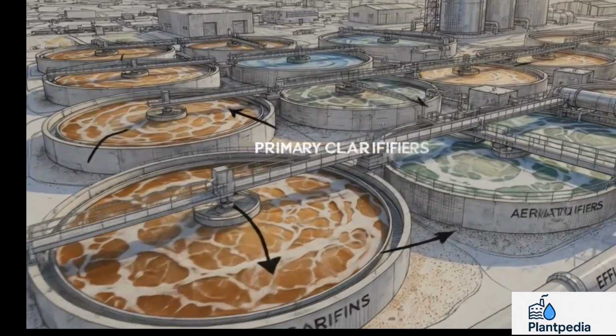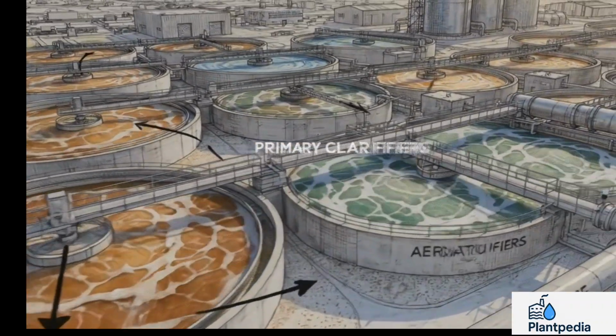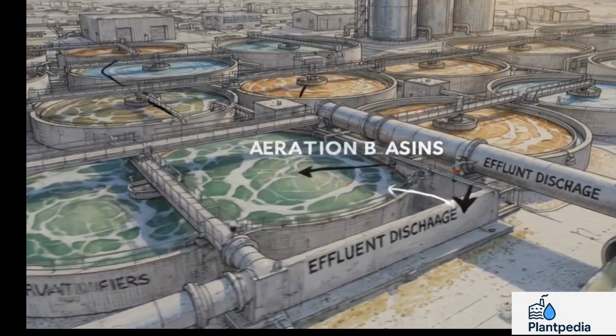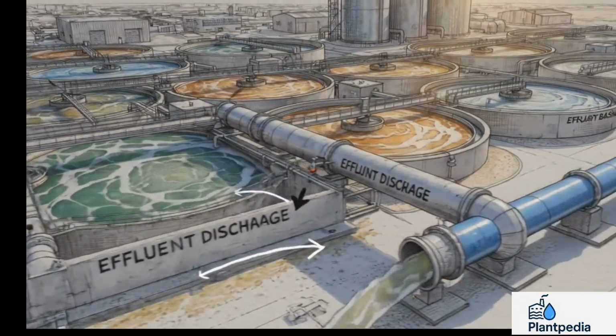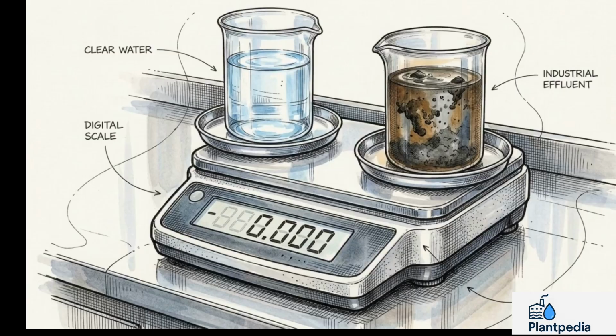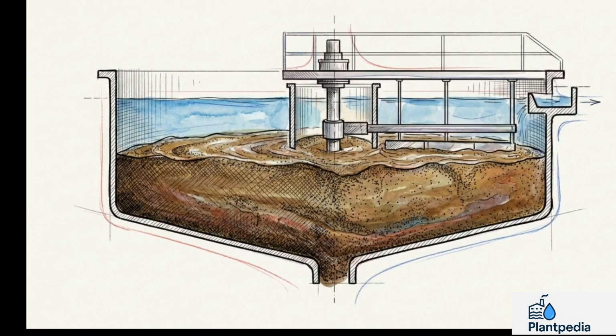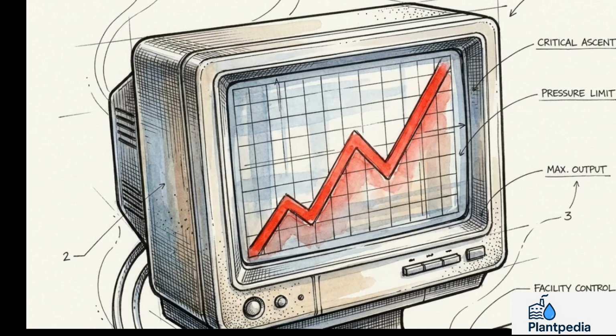Operating an industrial wastewater system, whether it is a standard water treatment plant, an effluent treatment plant, or a zero liquid discharge facility, presents a strict chemical balancing act. Injecting the incorrect chemical coagulant creates an immediate chain reaction of operational failures. You will see plummeting water clarity, massive spikes in sludge generation, and rapidly inflating daily operating costs.